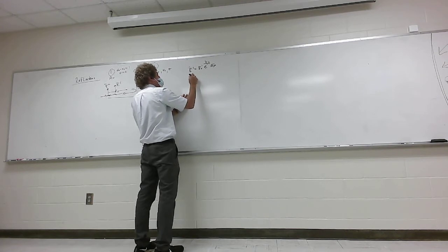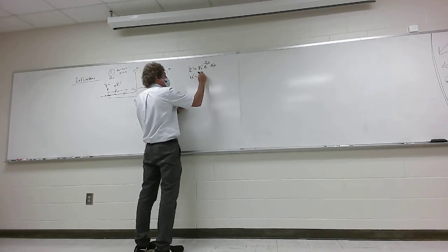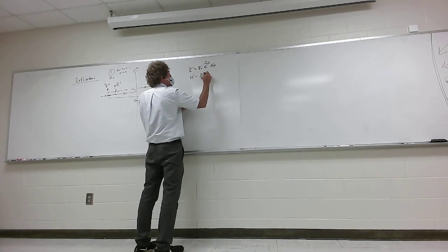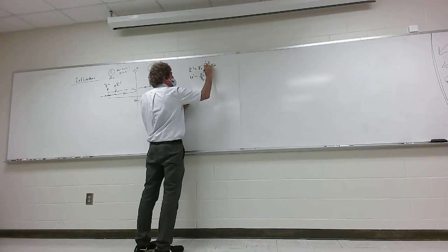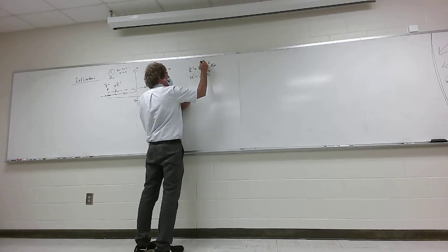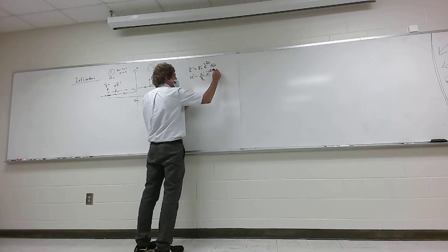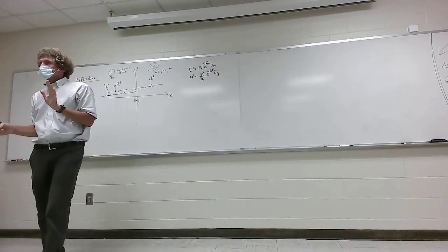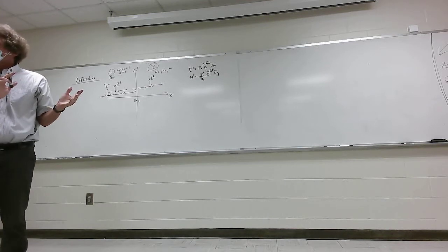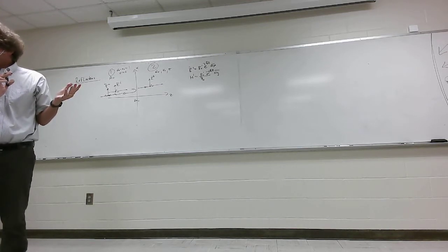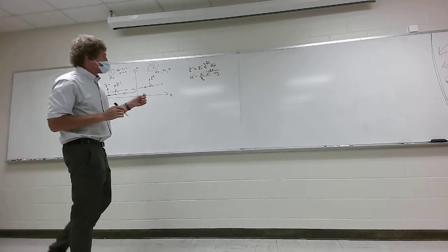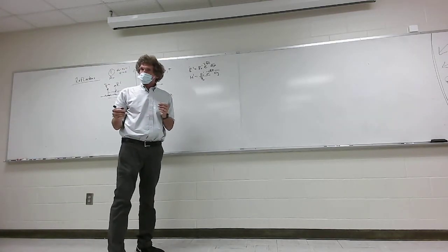And it would have a corresponding H field incident, which would be E naught incident over eta, and I'll call this eta naught here, and it would be times e to the minus, well, if it's air, it's just beta anyway. I might as well just go ahead and make it minus j beta 1 z, ay. Now y'all see what I've done there. That's the incident field in the standard way Dr. Wentworth's book likes to write it. And I made it air so I don't have to worry about that alpha term. Okay? Don't worry about the intrinsic impedance being complex. That's just eta naught. Got me, class?